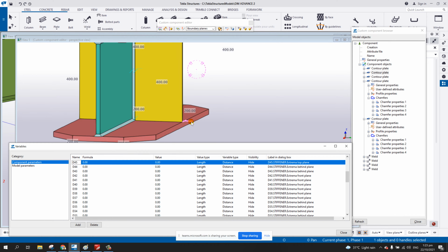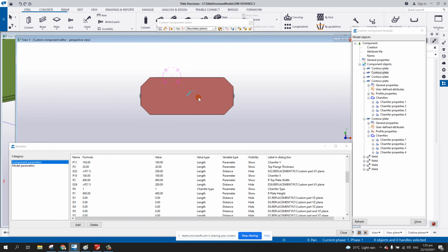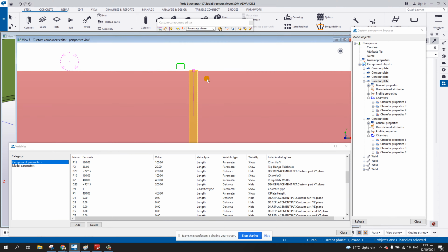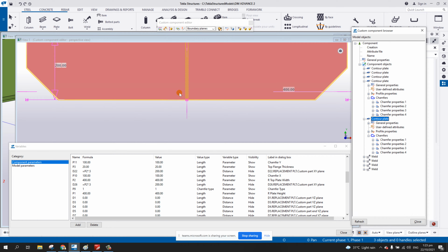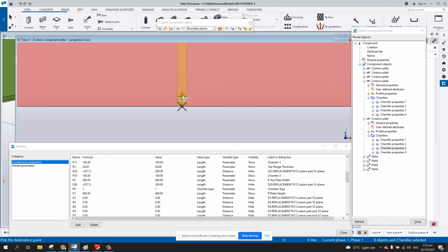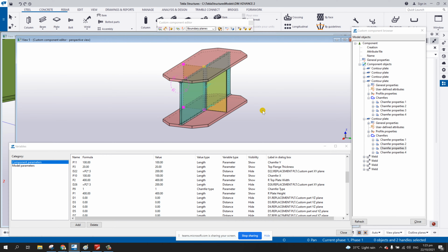Okay. Now before I bind this one, I think I better delete this one, and then I'm going to move first to, let's say, 10 mm. I'm going to move this one 10 millimeter, and then also this one move 10 millimeter, and then I'm going to start the binding so that I will have that 10 millimeter gap, so that I can control.